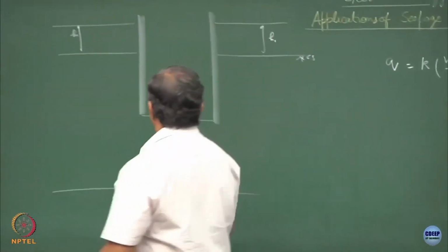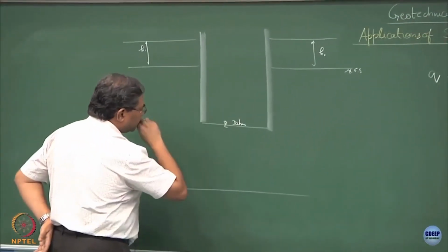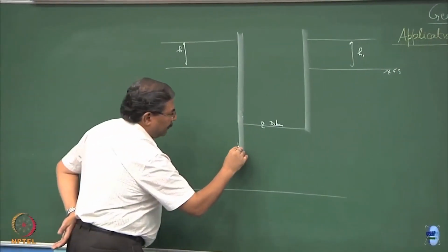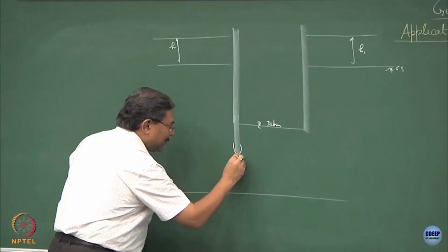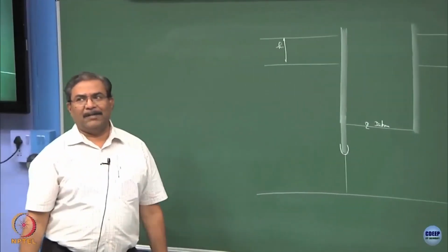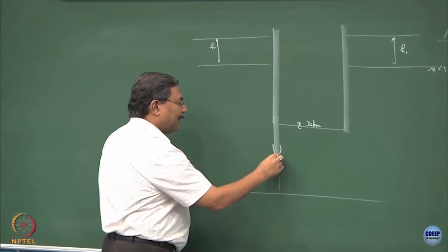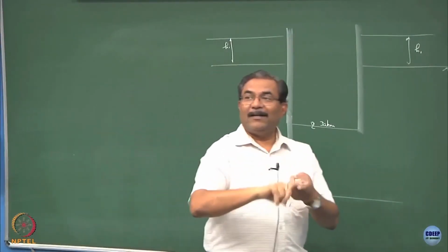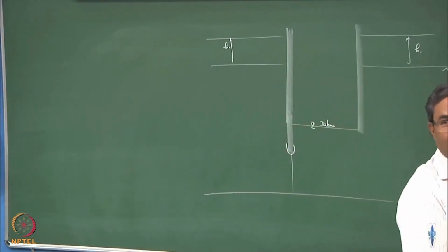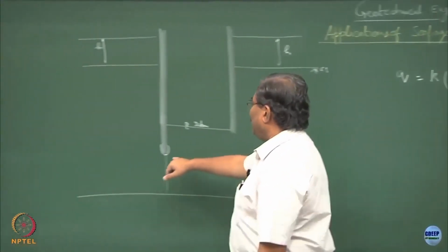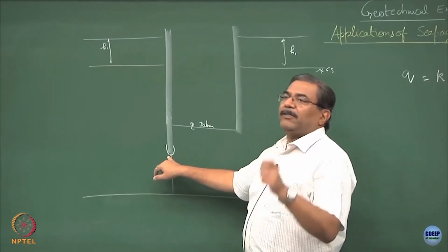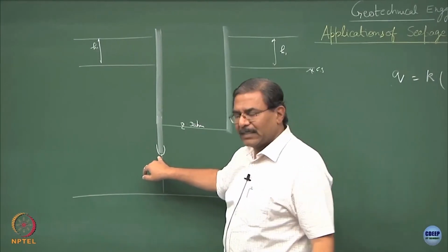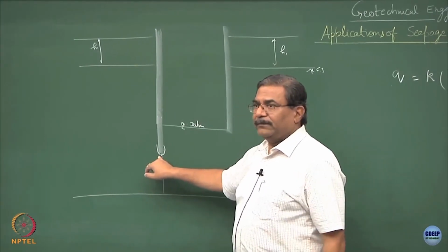So, what we are trying to discuss over here is, say this is a sheet pile, this is the flow line, and then you want to draw an equipotential over here. I said no harm, but look at this point. This point is acting as a flow line also, it is acting as an equipotential also. You are defying the phi perpendicular to psi concept. So, these points are known as singularity points. That means we do not consider them in analysis, but you can't defy them also because they exist. Fine, clear?